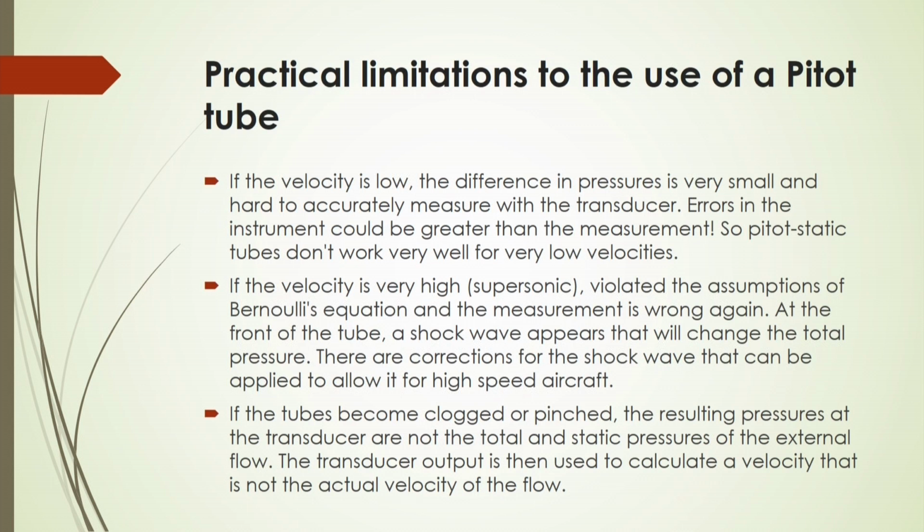At the front of the tube a shock wave will be generated, and that will change the total pressure. There are corrections for the shock wave that can be applied to allow its use for high speed aircraft, and that is why you have to consider the correction factor whenever you are going to use this for high velocity.